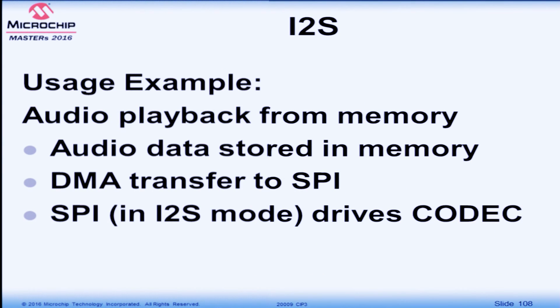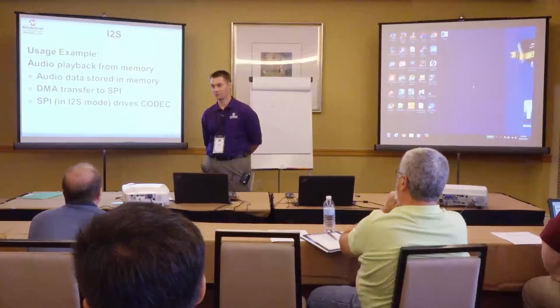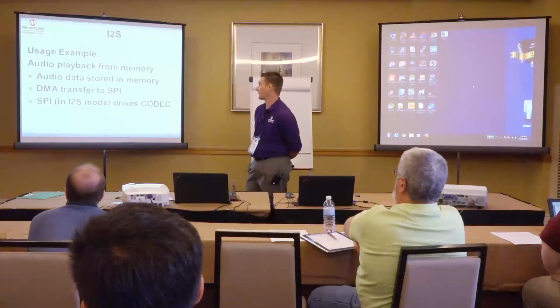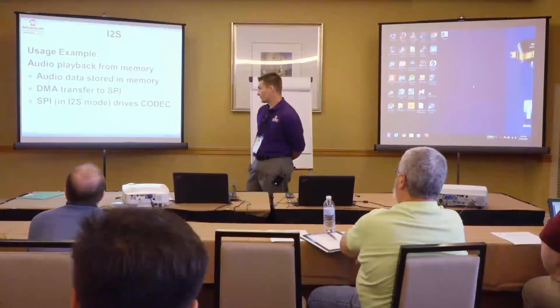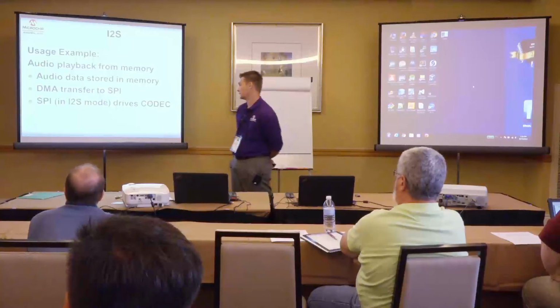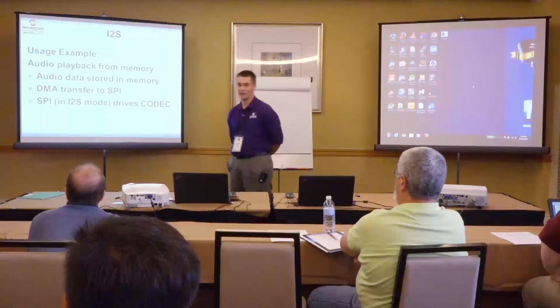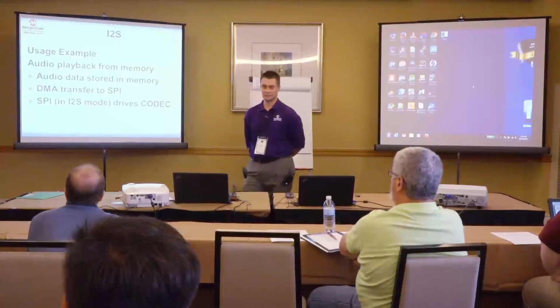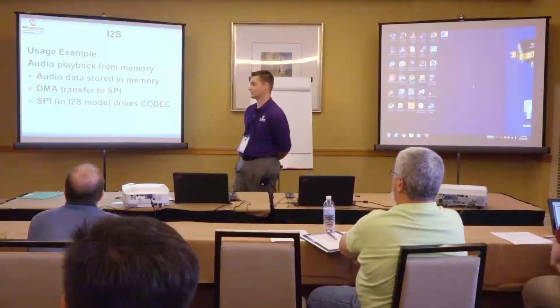So a quick usage example of I2S would be maybe doing audio playback from memory. Maybe you have a product that you want some kind of confirmation from a button press or some event happening, a little ding or a beep or a bleep or a voice, whatever it would be. You could put the audio data in data memory and then use the DMA to transfer it to the SPI without needing the CPU or the core to do anything, which again is kind of the point of the class.